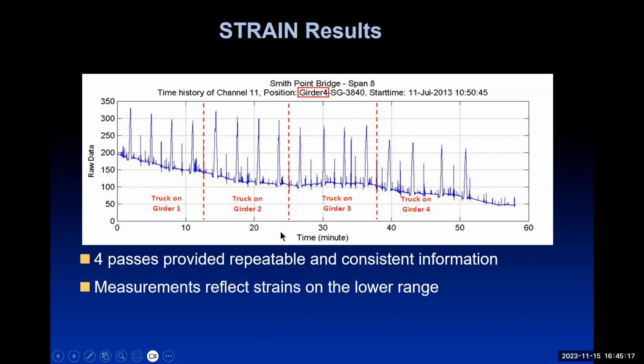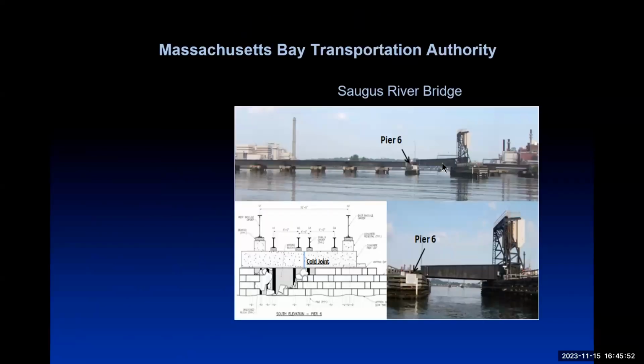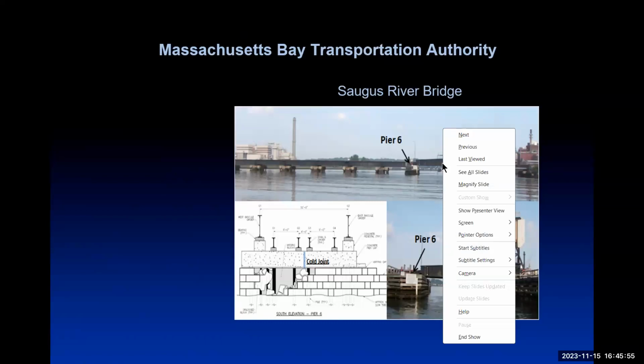of transit of the stress characteristic. Now, if we look at what that means, what we actually have was the amount of strain in the structure and the frequency in the span. So as we look at this, the strain was higher, and here it's lower. The strain comes down, and the frequency comes down as well. This is for a whole series of spans which were a similar length. So we got a good measure of what was actually going on in the structure itself.